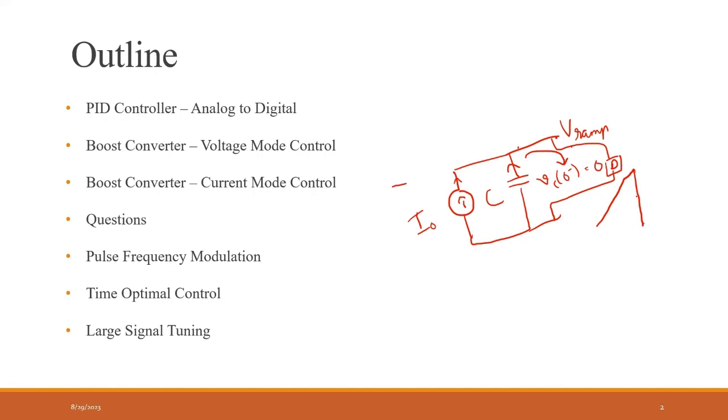So exactly, I don't know. These are used in commercial ICs, and these ICs will have some sort of way to do it. But the basic thing is you have this I naught current to charge it. Once it is fully charged, this should not flow and it should get discharged from here. Once the discharge is over, you start the I naught again and it charges the capacitor. There might be some sort of switching system over here.